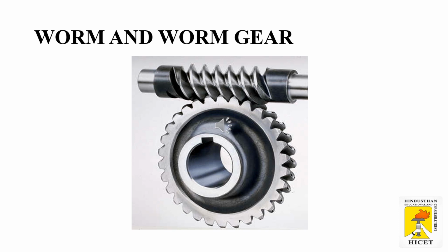Spiral gears, also known as crossed helical gears, are used to transmit power between two non-intersecting, non-parallel shafts. The teeth of crossed helical gears have point contact with each other. Therefore, they are used for light load and low load applications, that is, machine tools, camshaft and oil pumps on small IC engines, feed mechanisms, etc.